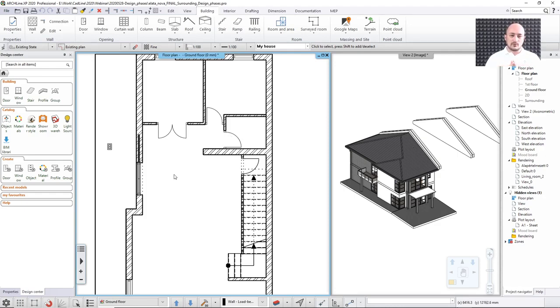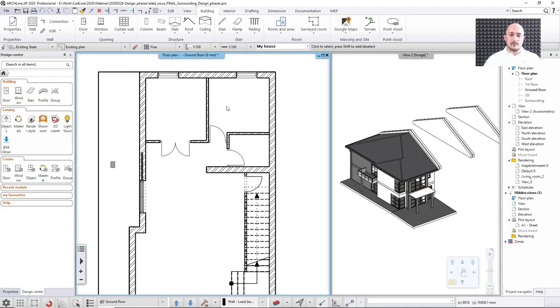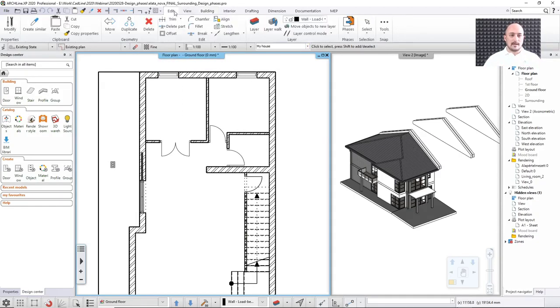And now if I would like to remove things, here's a practical advice for walls when you do not want to remove them fully, I will show you that as well. You should start working with those items and start marking them to demolition. So what I will do, I will just go here and say, okay, edit phases, change to demolish for perhaps this one, this one, this one, this one. I do not even need to mark the doors to demolition separately, because if I remove the wall, obviously it will remove the openings as well, and so on.